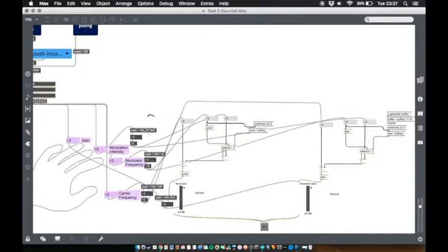So it's quite a bit messy, but the scale objects I've used are highly modifiable. If someone else were to use it, I'm sure they'd probably change it themselves. This is what I felt comfortable with. This is just the standard analog input range for the LDRs, and I've got 170 to 3000 for the modulation intensity, because I just wanted that really dramatic range. But for things like modulation frequency, when it gets too high, it starts to sound a little bit distorted, so I decided to have that scaled at a slightly lower range.